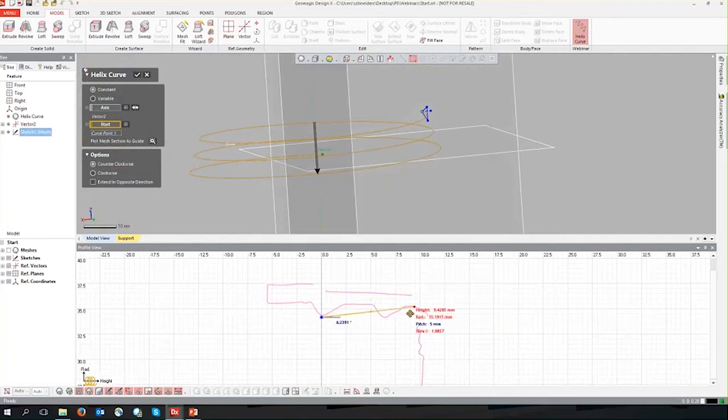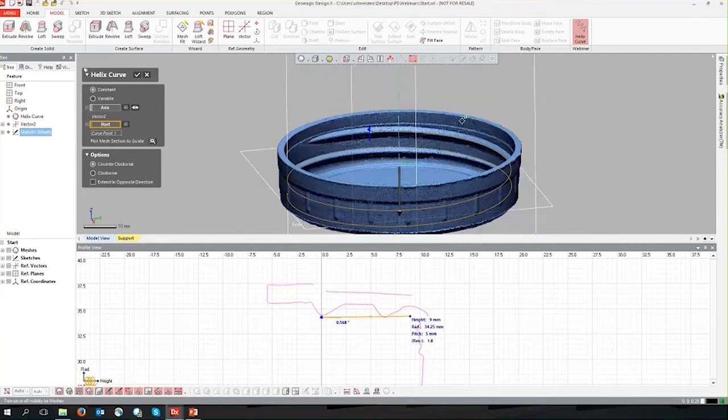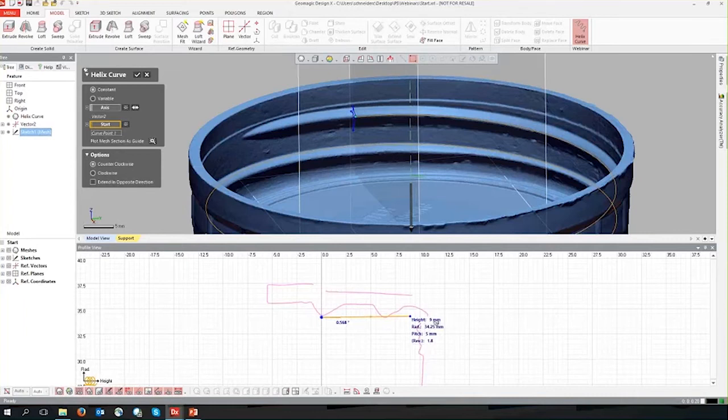This is where the 2D profile is nice, where if we do see a kind of funnel shape here, we can use the top of the teeth as a guide, right? So turning our mesh back on. Looking nice. Here we have some other parameters that we talked about in our setup tab. We have our height, which is the top to bottom height of the helix. We have our radius, so this will be the radius at this point.